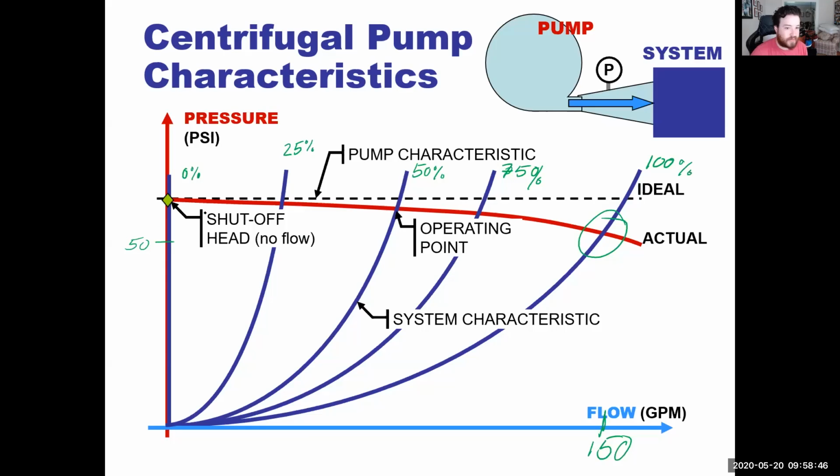These kinetic pumps, you can let her run at this shutoff head and she won't have any problem. Eventually, because the impeller is putting so much kinetic energy and the fluid is not moving in there, eventually you'll actually boil the water inside of that casing. And then it might explode. But that'll take a long time. All right. But you'll have no flow. You're just going to have this constant pressure. All right. That's the biggest thing. This is shutoff head right here.